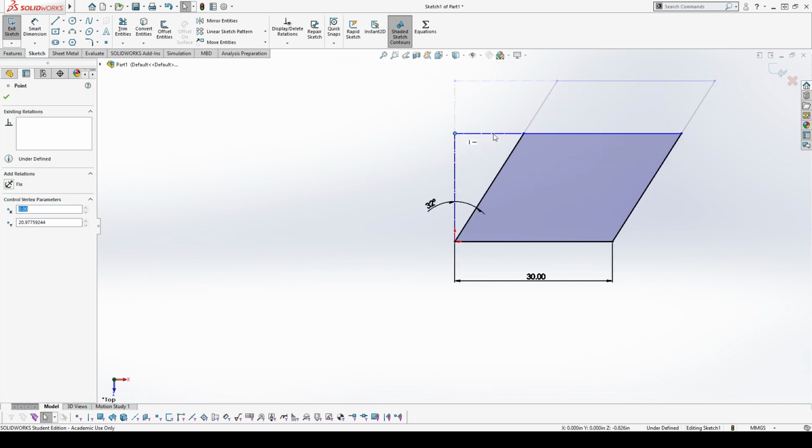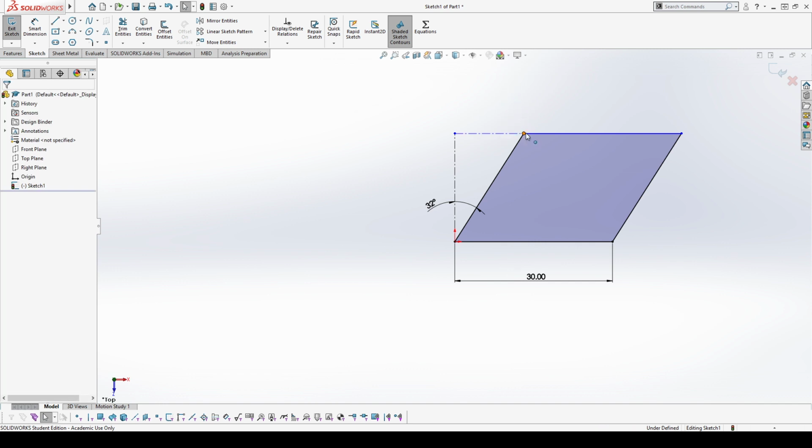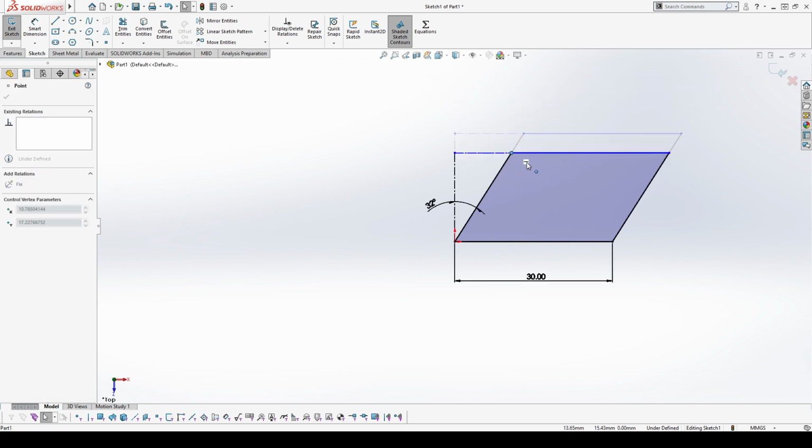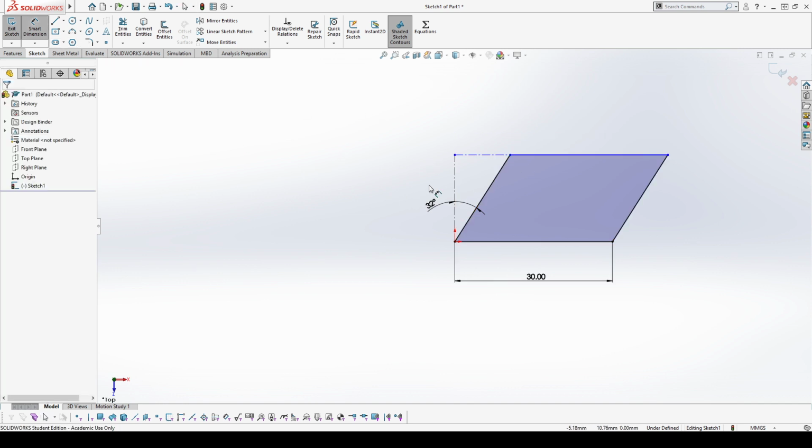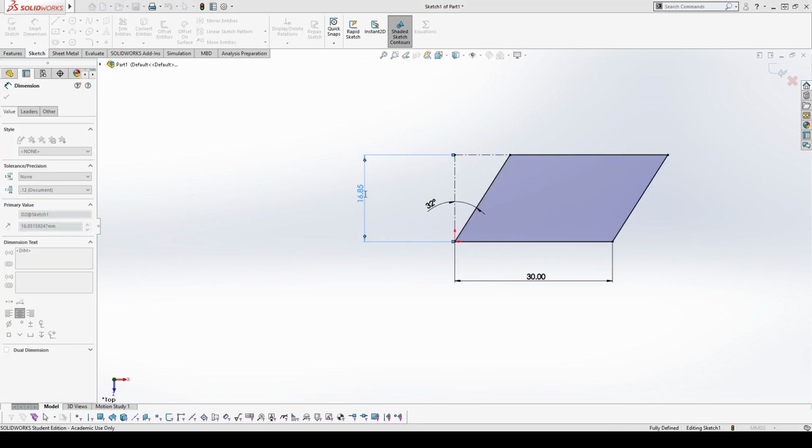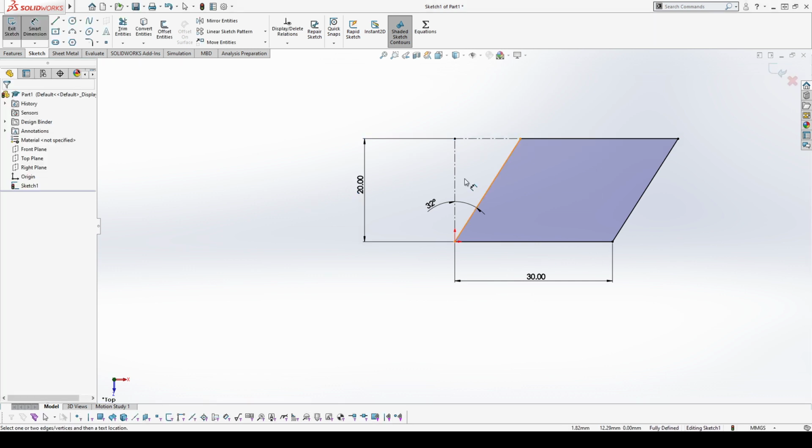You can see that as I drag one of these points, it drags both of those lines and they stay together. And then I can just dimension that this construction line is 20 millimeters long. So this is 20 millimeters long, which means this line here is 20 millimeters away from there. Now I actually have a physical piece of construction geometry within my part file